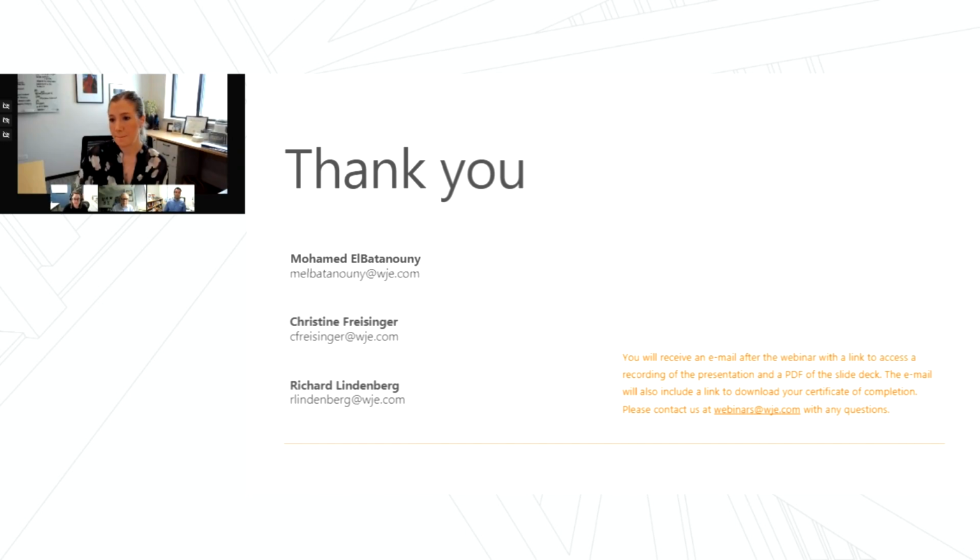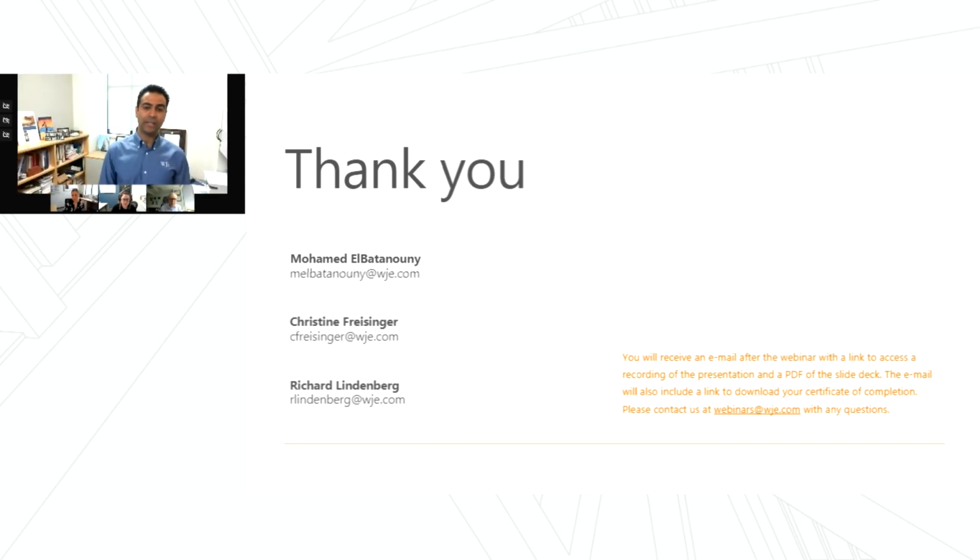Yeah, I can take that one. And yes, you can. And we showed this in the case example for Sue, where we just installed the columns right under the three beams that were supported. So you can definitely do that. You can also do it if you have beams and you're just stiffening the beams. You can just stiffen the beams that are directly in the areas where you're trying to reduce the vibration. And that will likely solve the problem.